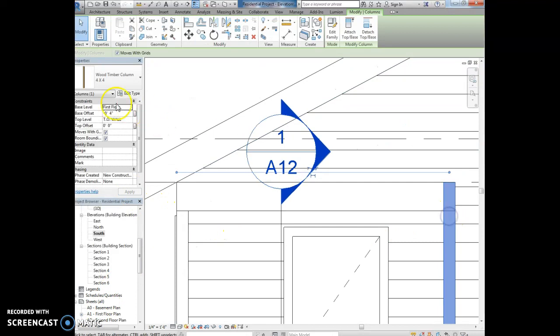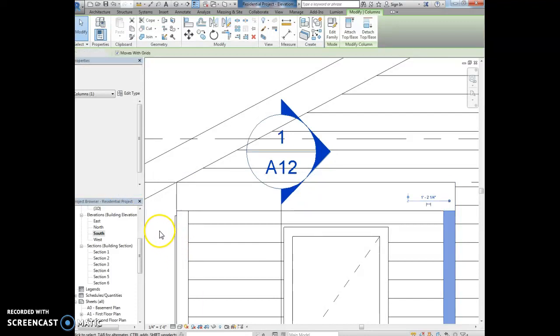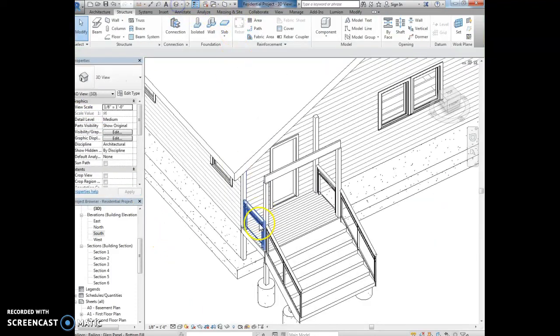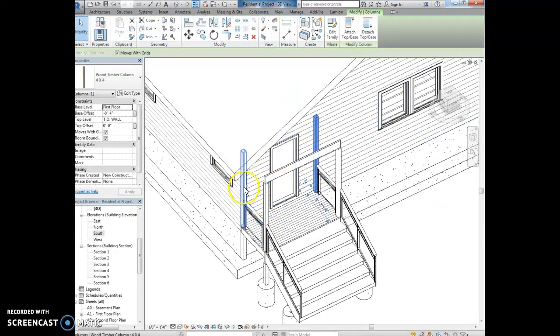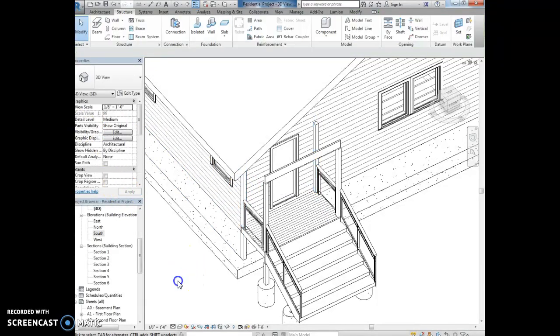And then we're going to click on this one, and this will also be -9.25 inches, and hit apply. Okay, go back to 3D view. Make sure we select these posts back here and change their top offset also to -9¼ inches, and apply.